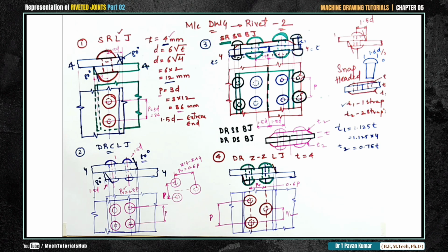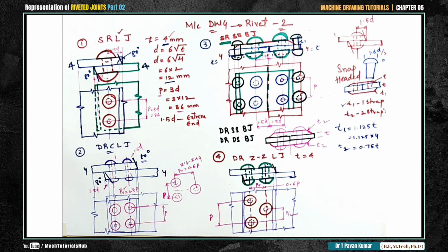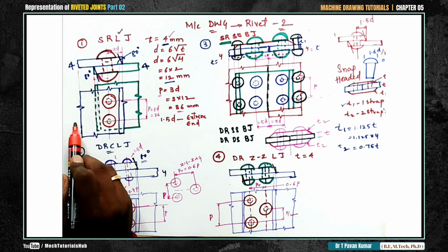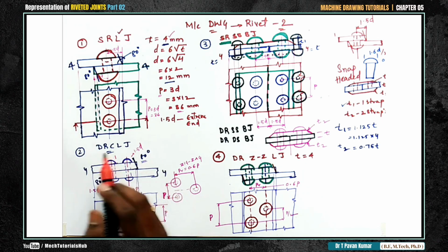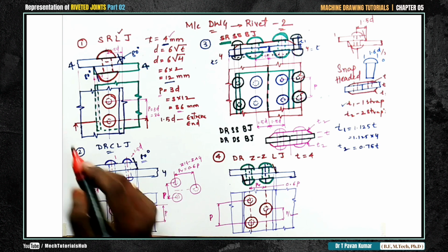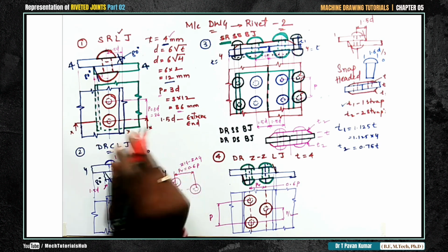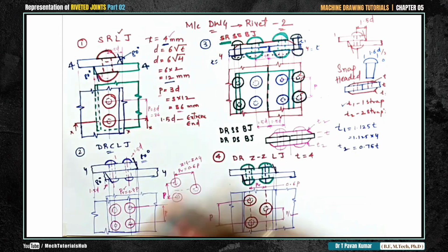For example, we'll do hatching on the front view and on the top view in some cases. What does it represent? It represents the cut section. For example, there is a cut section at this point from here. This is how we'll represent a cut section. You can give PP as the name, or XX is your cut section. If you cut the portion here, this portion will get removed. Only this will remain. When you view from the front, you could see both the thicknesses again.